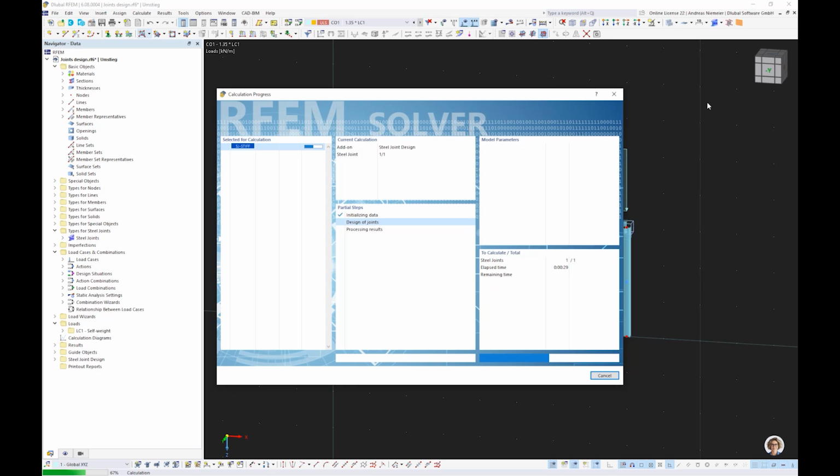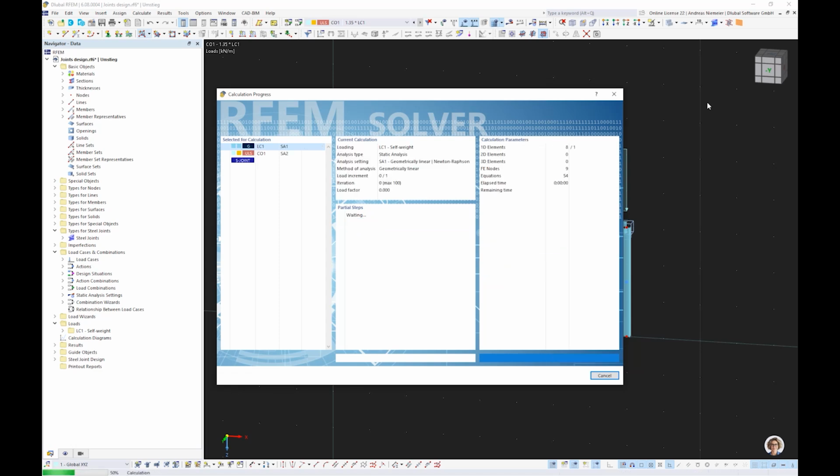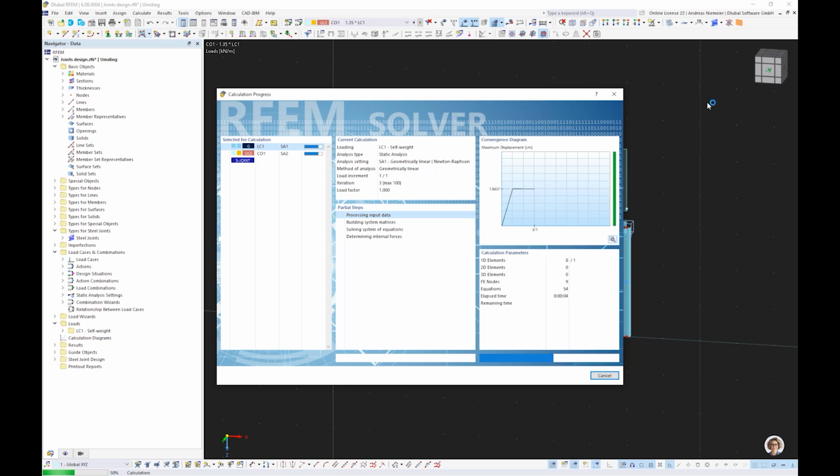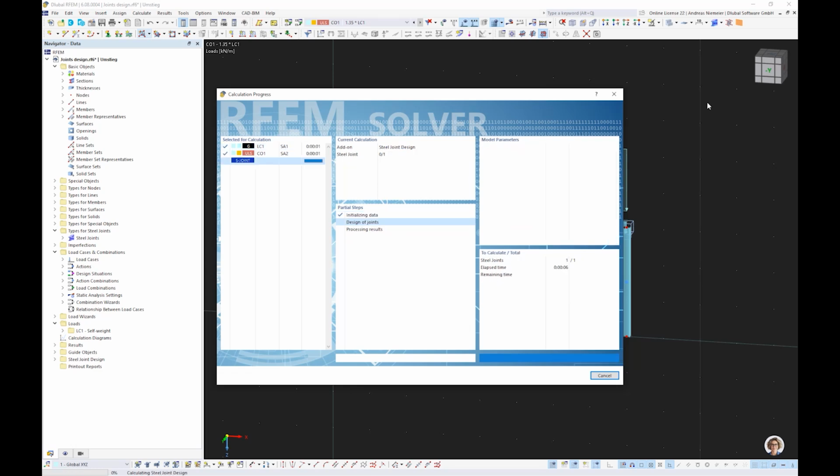Additionally, because this technology models a shell model behind it with nonlinear material law and checks the strengths in the end, this allows you to apply normal axial force, shear force in Y, in Z direction, torsion moment, My and Mz bending moment. So you can apply all forces. It's independent. It's allowed. Yeah, and we use this with this concept. Further, you can analyze not only forces but also unit deflection. So we can calculate stiffnesses from it, and now new also assign it to the global model.